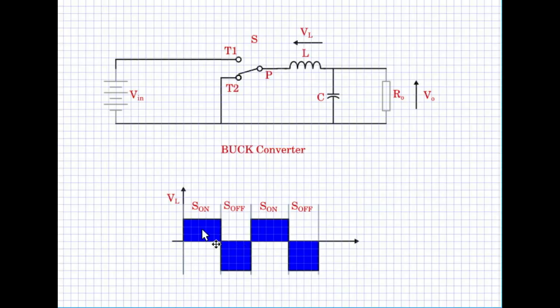So it is very, very important that there is volt second balance in an inductor, and in the case of the capacitance, the average current should be 0. If there is an average current, there will be charge build up in the capacitance. So in the case of the capacitance, amp second balance should be there. In the case of the inductance, volt second balance should be there. These two are very, very important concepts which I will explain shortly.